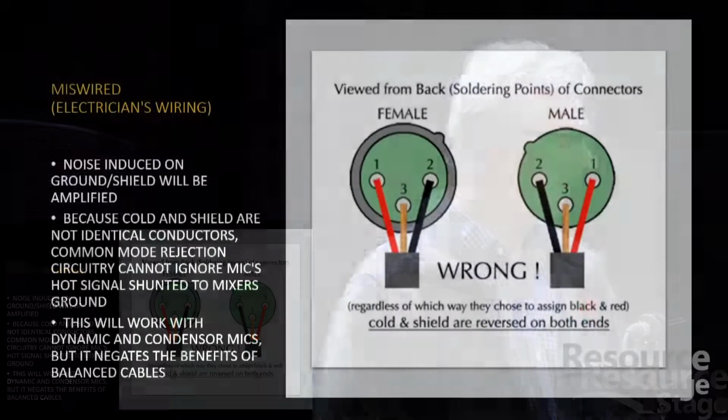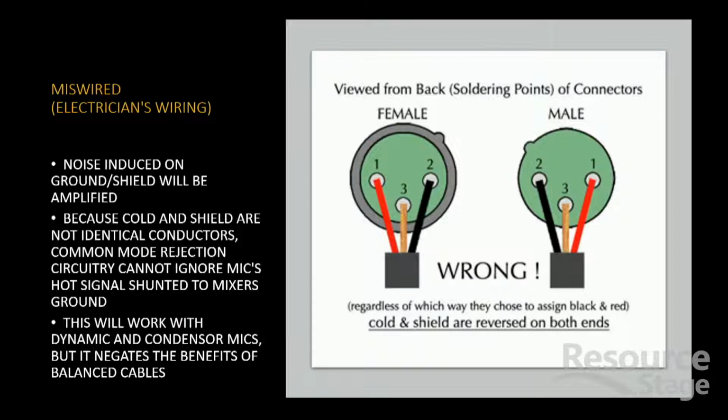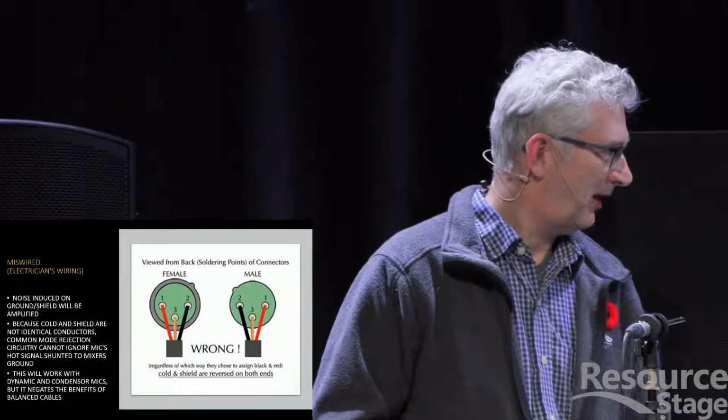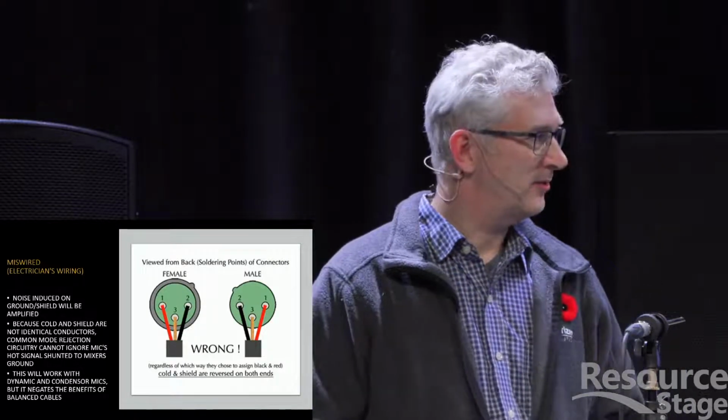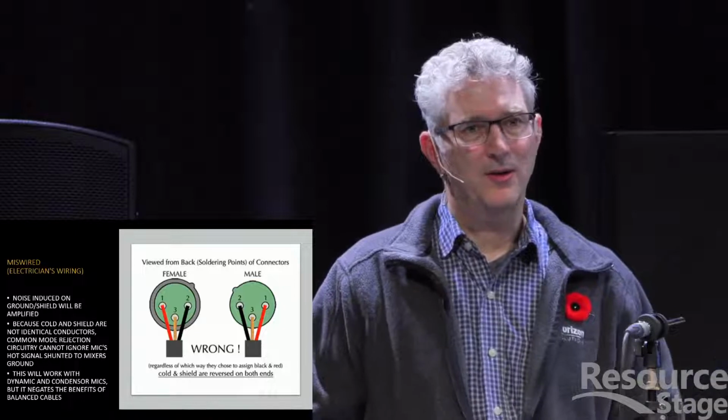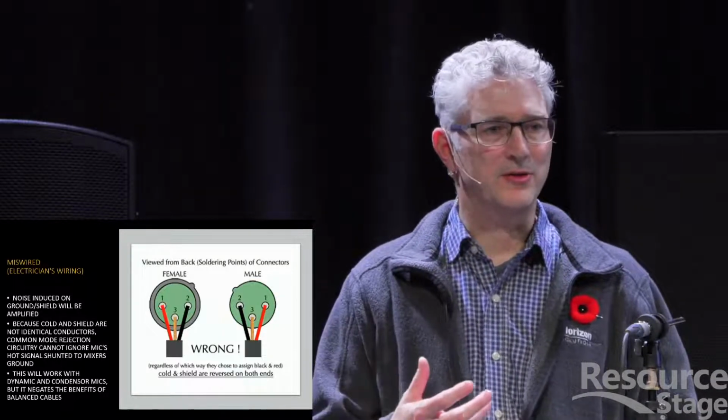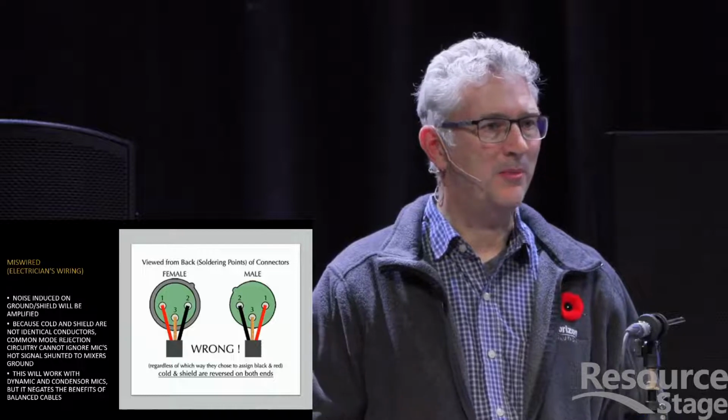This next one, we see that it's electricians' wiring. They've wired the shield to pin 3 because that's where the ground is on your electrical plug, and pins 1 and 2 are wired to the signal conductors. This is going to cause noise on the signal because between pins 2 and 3, the two conductors that are being used are not the same wire.